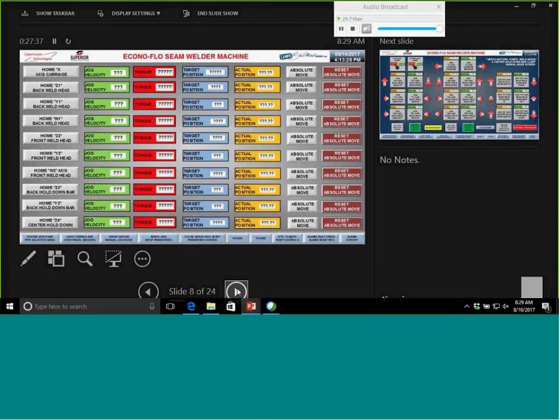Here's a screen that we have for a homing routine. We can adjust and modify the jog velocity, the torque, the target positioning, the actual positioning, and absolute moves. And so we have 10 axes, and we have this functionality for all 10 servos.